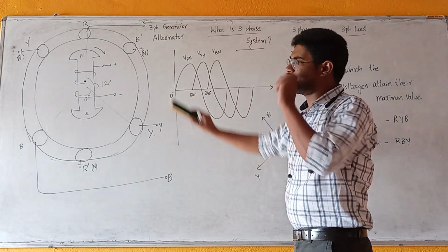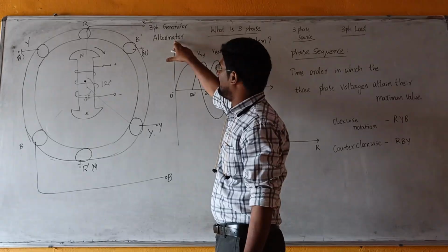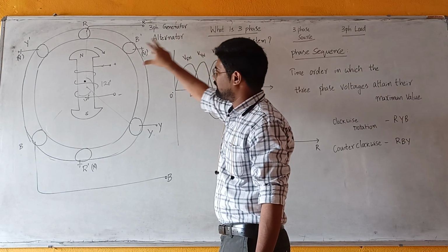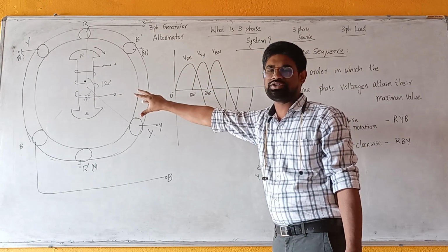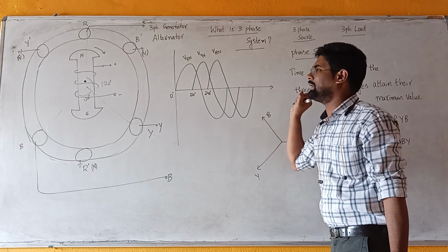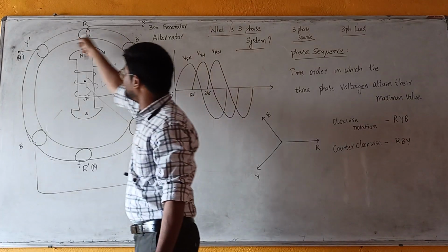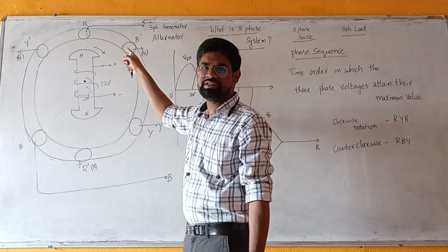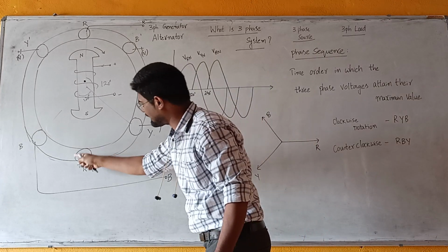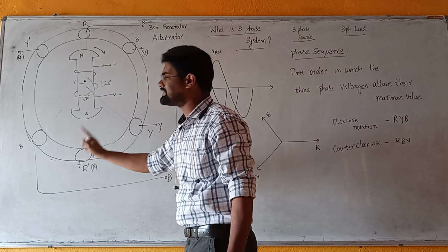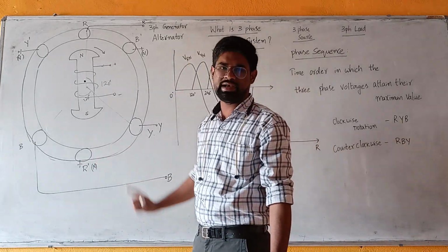Now what is this three-phase machine? This is an alternator, a three-phase alternator. From this alternator we will get electricity. From this three-phase AC machine we will get three-phase AC supply. Now what is the operation involved? This is the stationary part. The stationary part is an armature. It consists of 3 sets of windings, and we are using circles here. A circle means it is the conductor. We use a circle to denote a conductor, a winding.